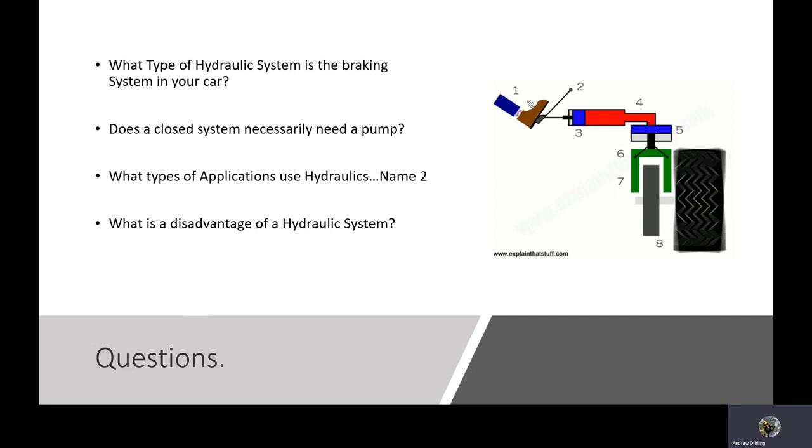The disadvantages of hydraulic systems: well, they are expensive, the fluids can be hazardous, and you can have messy leaks, and some of the fluids actually are a fire hazard as well. Plus, you can have cross-contamination of fluid into some things like plastics or food, which would not react very well to hydraulic oil, as you can imagine.